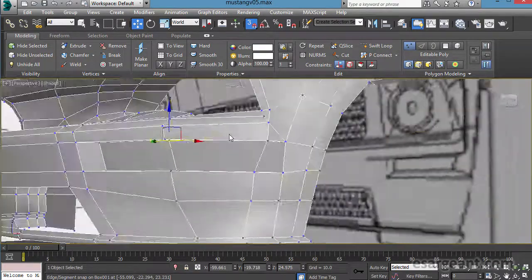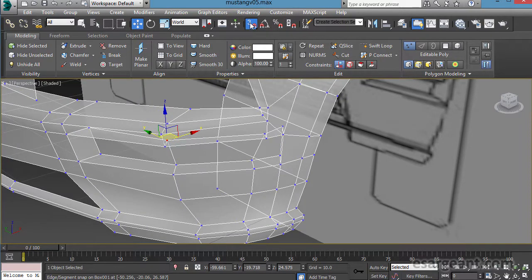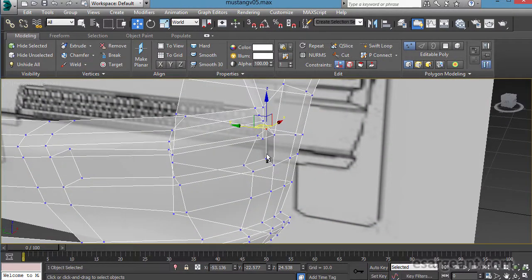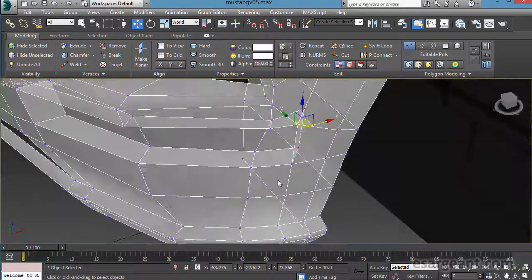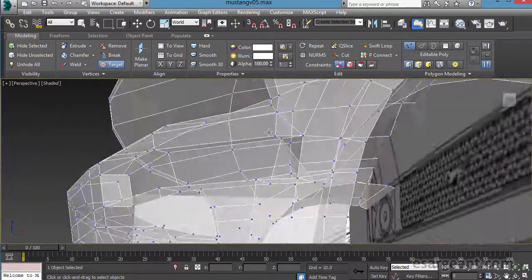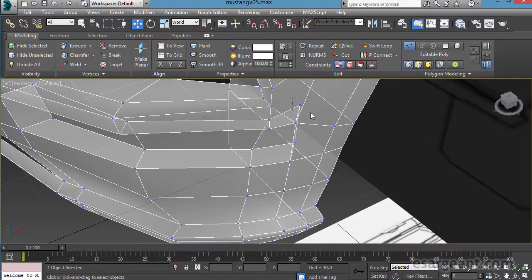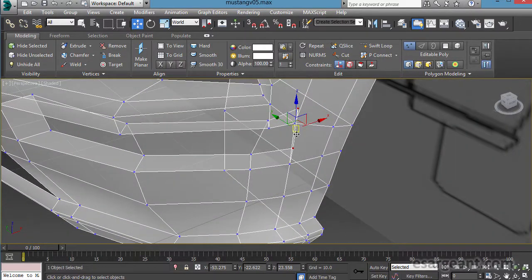this. What I need to do though is fix this interior portion here where I've got the leftovers from this extrude. And what I could do is take the easy route and just do a target weld and just snap those into there to continue that geometry along. But then I'm going to build more tris in doing that. So I think what I'll actually do is sort of bring them in and roughly align them to keep those quads in there.